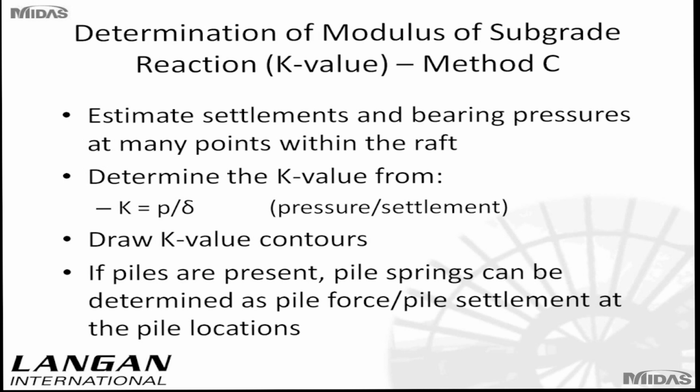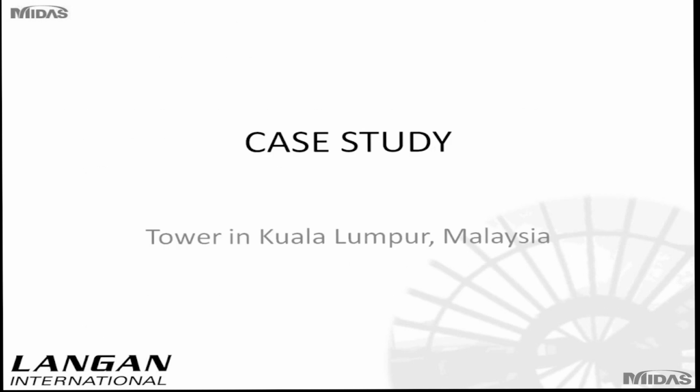Now, if we're talking about the case of a Pile-Raft, then typically you would also use pile springs, which you would determine as pile force over pile settlement at each pile location. And these results you would then provide to the structural engineer.